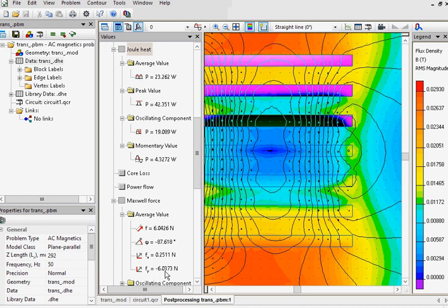Please note that all field parameters are harmonic functions changing in time. Field lines are displayed for some specific moment of time. And for the color map you can use momentary values, root mean square values or peak values. The default is RMS values, as you can see it here.